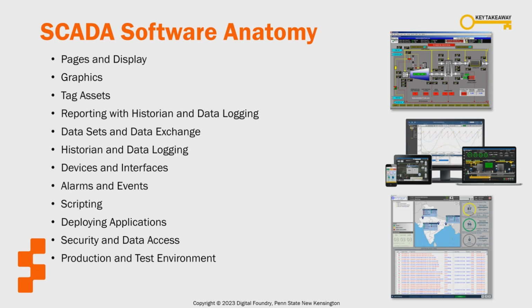Tags are the process variables for your application. Use tags and their properties to set up the data model for your processes. A report page provides predefined report types designed to analyze the performance of the equipment in your facility. SCADA systems may have built-in internal databases or may connect to an external database. A data historian is a type of time series database designed to effectively collect and store process data from a SCADA or automation system.